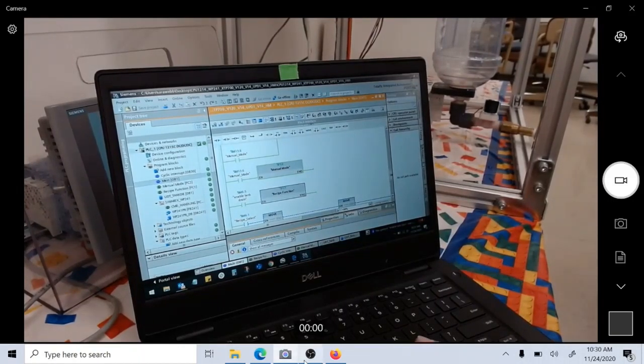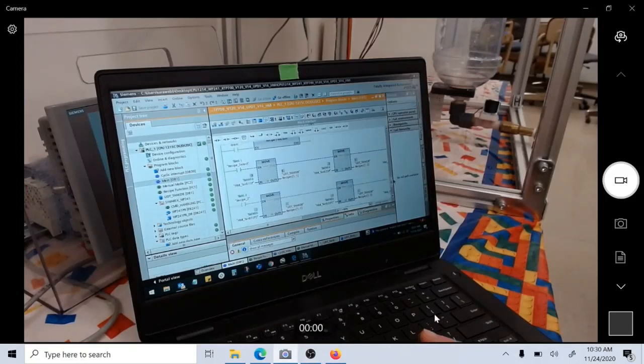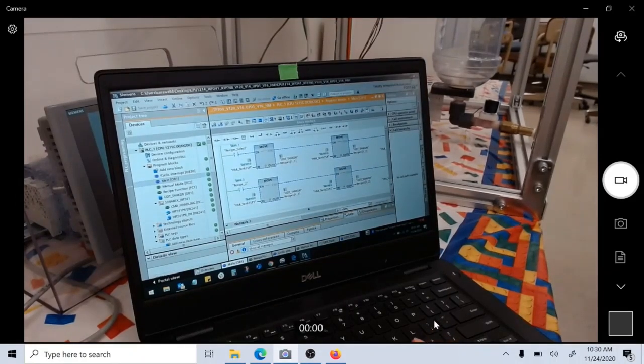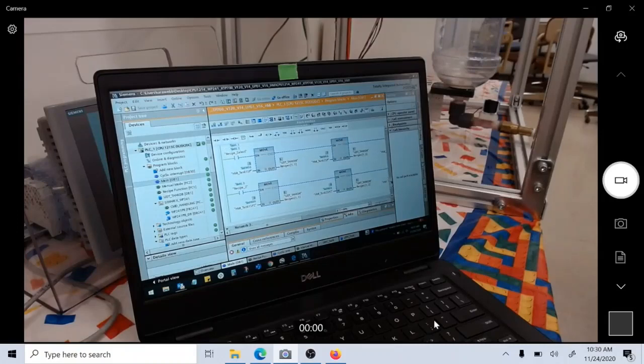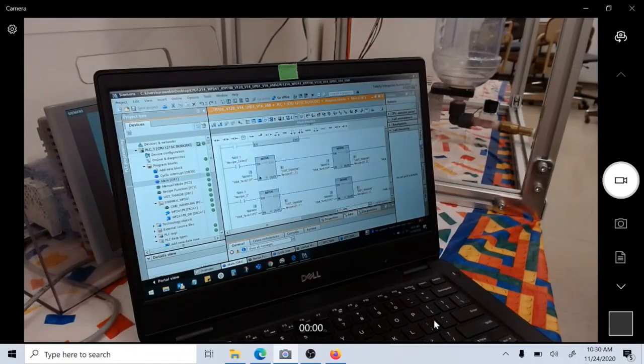And then further down, I'm sorry, the way it's written to allow the operator and the HMI panel to set their values is simply moving that HMI set point to the recipe array. And you see this in this rung here. Actually, these last two rungs are how that's accomplished.